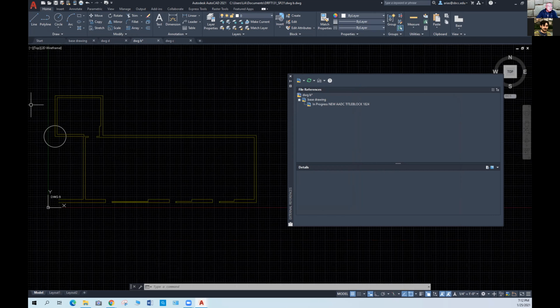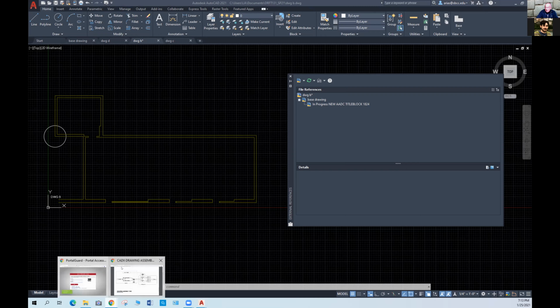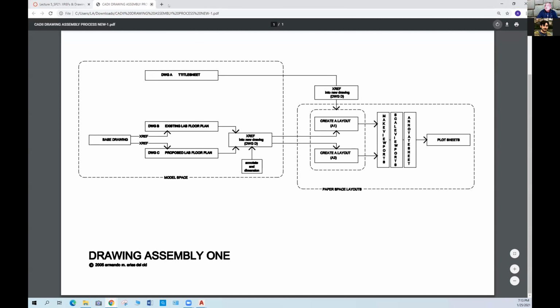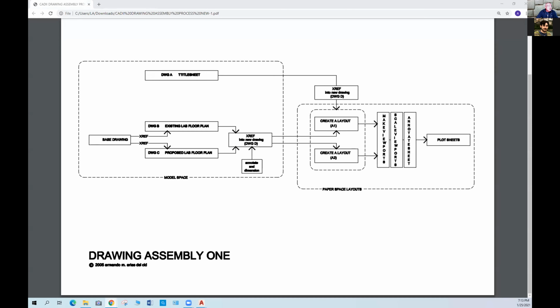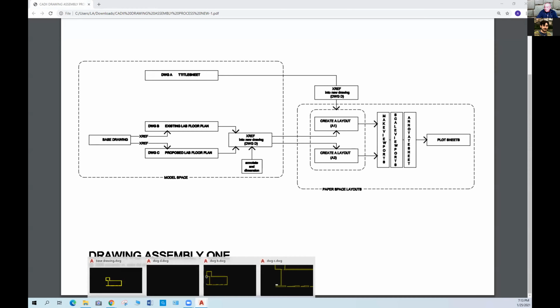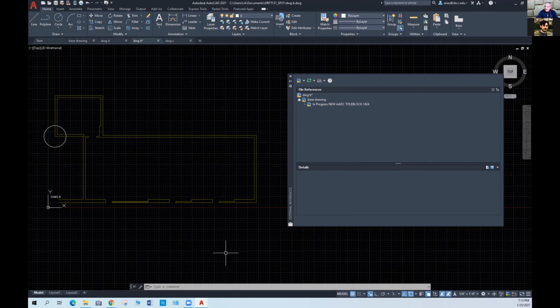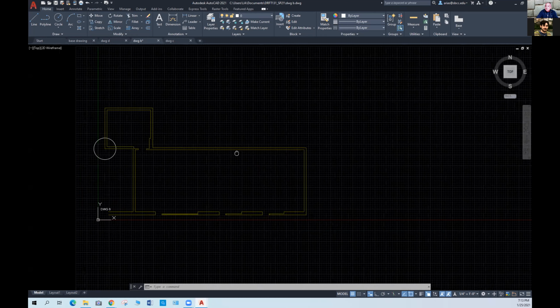And it's an important difference because if the purpose of the exercise for us is to not see the XREF in AutoCAD, but I might need to have it back at some point in time, then the best thing to do is unload, not detach.